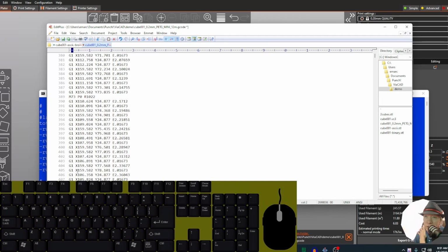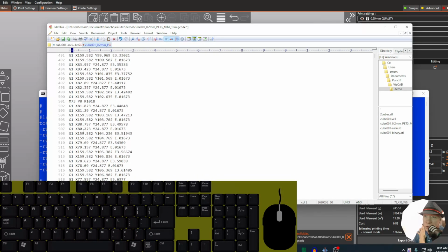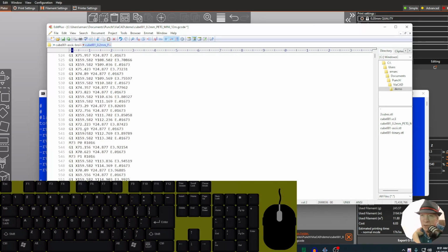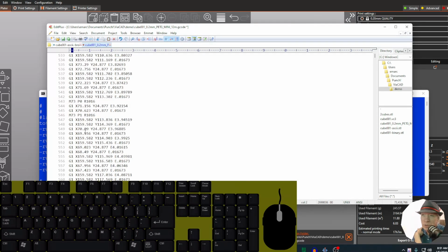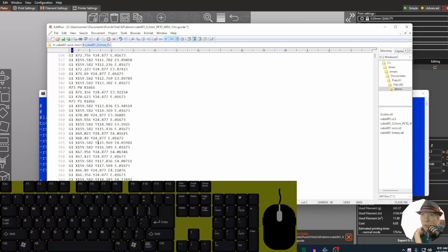So it doesn't necessarily draw a line. If you're going from here to there, it might go faster on the X and actually come around that way instead of a line. G1 makes it a linear line from point to point. So almost everything is going to be G1 commands. G0 is just for moving the head around and getting it there fast. G1 is actually doing the work.